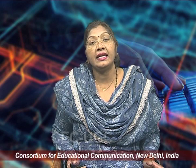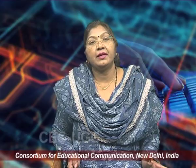So the surface acoustic wave resonator, that is the SAW resonator, is a type of resonator that uses surface acoustic waves to generate a resonance similar to the crystal oscillator, and it can be represented by an equivalent circuit that includes an inductor, capacitor and resistor. This circuit model is used to understand and analyze the behavior of the SAW resonator in various applications. What is the operating principle behind it?